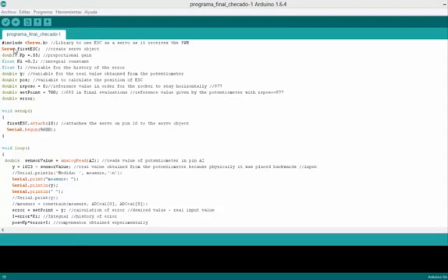In the next parameters, we create a servo object, and we write a proportional gain of 0.55, an integral constant of 0.2, a variable for the history of the error, and y for the real value obtained from the potentiometer. The variable pose is to calculate the position of the ESC, and the variable reposo is the reference value in order for the rocker to stay horizontal.